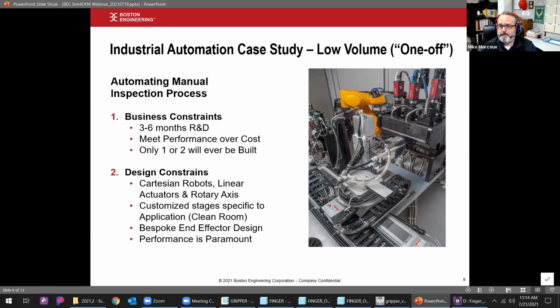So what are we doing in terms of optimization? We're doing part optimization. I really want to get that cycle time down, but I also want to make sure that I'm keeping that part within the depth of field. So maybe I'm looking at those classic trade-offs of weight and stiffness. How fast can I move this through here? Can I maintain that trajectory? Can I maintain that stiffness? Am I worried about things like vibration and modal? All those things have to happen very early in the design process. So that's two separate cases in terms of quantity and type of system, and the different types of simulation that get baked in the early stages of each design.